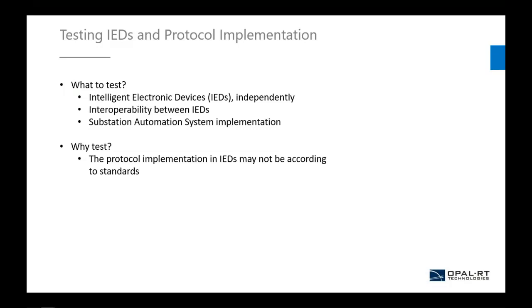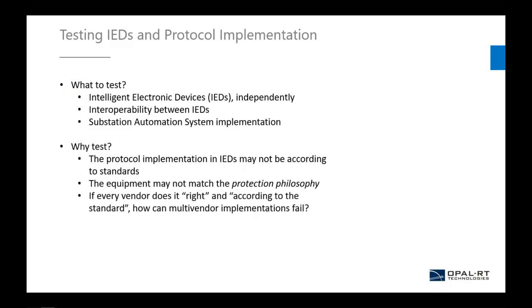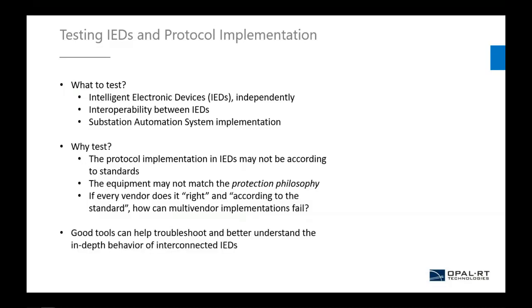Now, why should engineers test these features? One obvious reason is that the protocol may not be implemented according to the standard. Another less obvious reason is that the IED may not match the protection philosophy, and I'll get back to this point during my presentation. Finally, if every vendor does it, I quote, right and according to the standard, then why do multi-vendor implementations have failed in the past and continue to fail in some cases today?